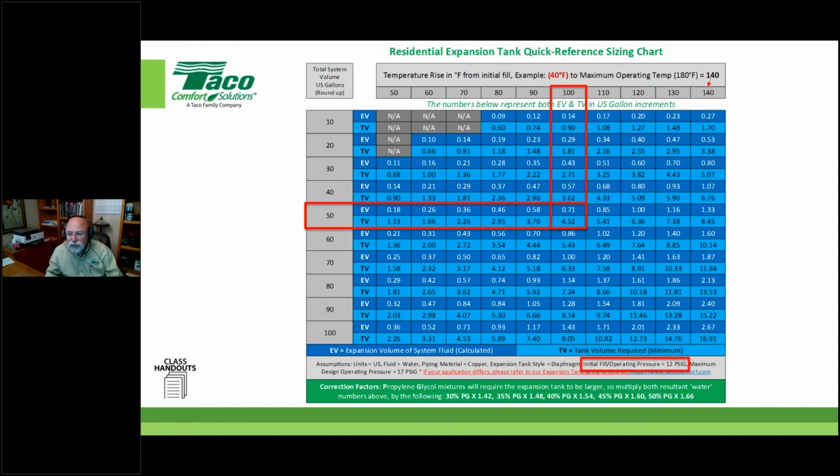Okay. Some other things down here, your initial operating pressure is 12. Maximum, notice I only let it go up 5 pounds. I didn't take it all the way to 25 pounds, right? So if I did, it would make the tank smaller, okay? But what I want is the reality. When I walk into a mechanical room and I see a design condition, I really don't want to see that gauge pegged out. That's my opinion. You do anything you want with that, okay?